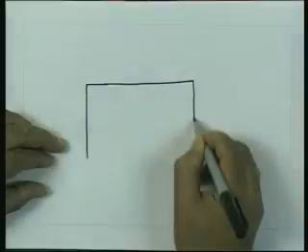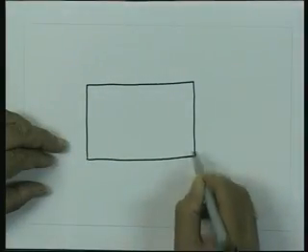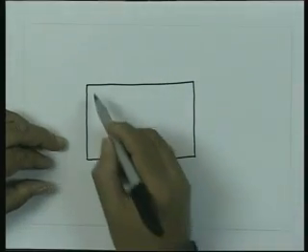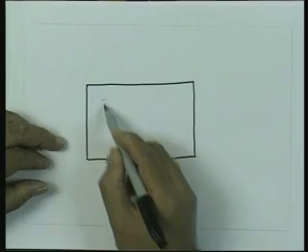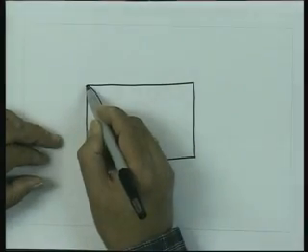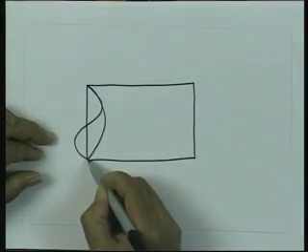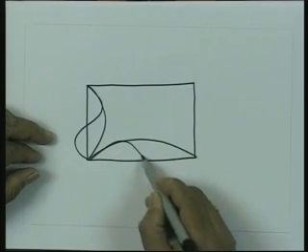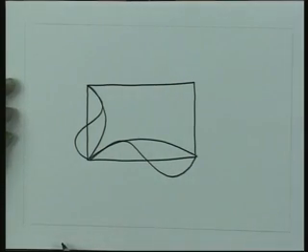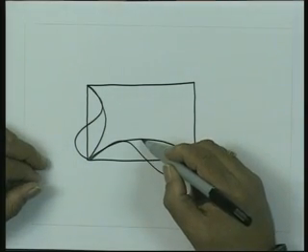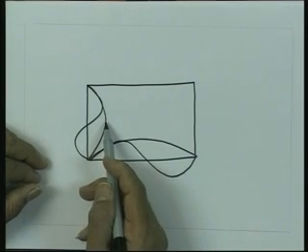If I look at the cross section of the waveguide, the Ez is 0 here, 0 here, 0 here. So, it had half cycle variation like that, or it could have a variation which will be like that. The same is true for half cycle variation in this direction, or it could be like that. So, the Ez is 0 at this point, and the maximum here if m is equal to 1, maximum here along this if n is equal to 1,